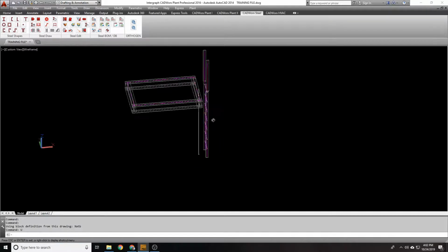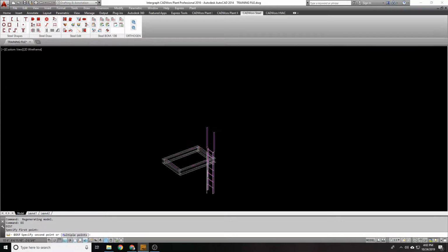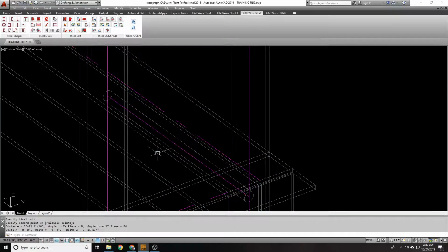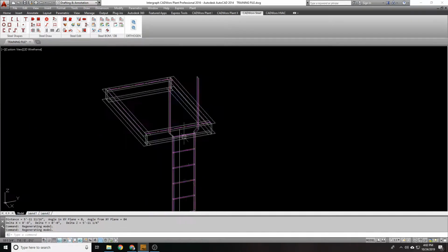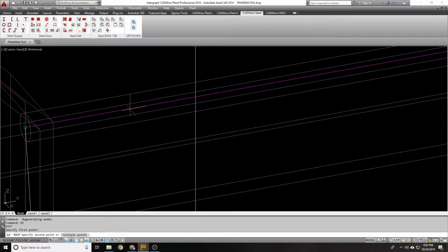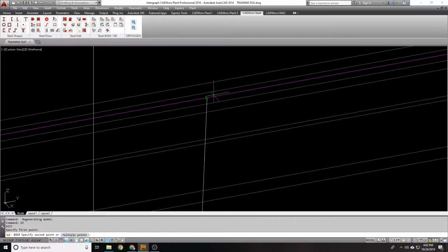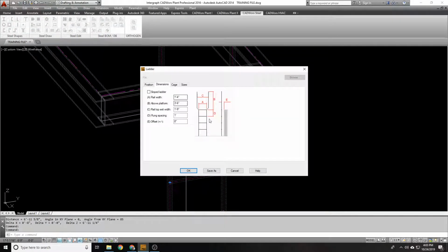All right, now, remember I was telling you earlier about dimensions not being exactly what they seem. Well, the dimension from here to here is, where's my Z dimension? Let's try that again. So we're going to go from here to here. Are we on the center? So look at what we're getting. We're getting 6 foot 11 1/4. But you can see that in this diagram, it's calling out that the top of that rung, which is what it's talking about, start and end point, right, should be 7 feet.